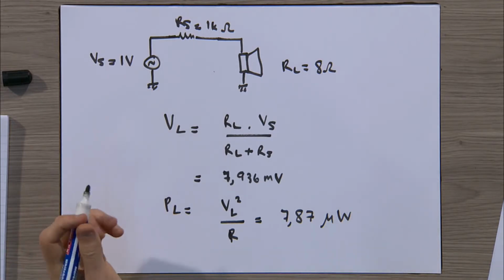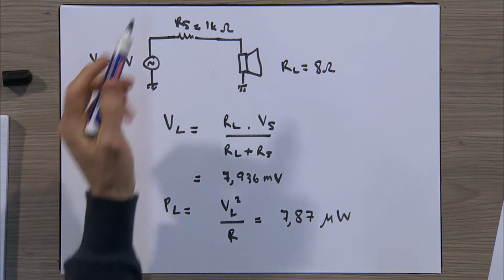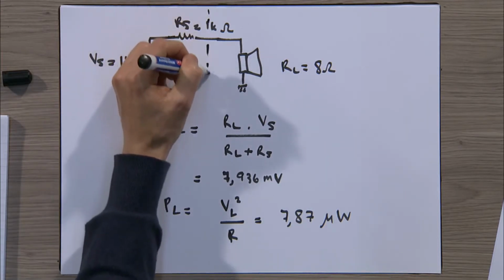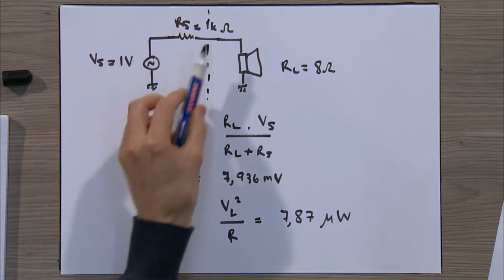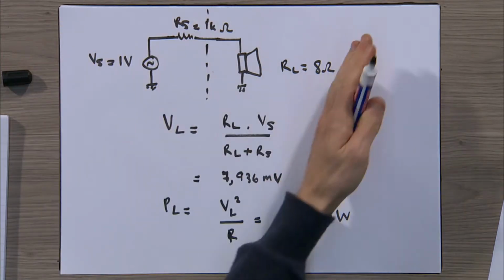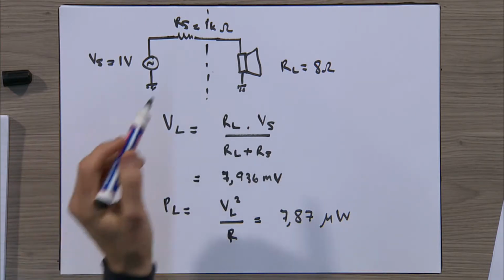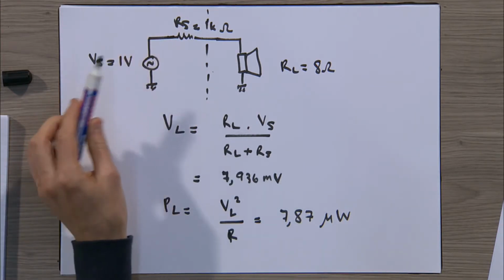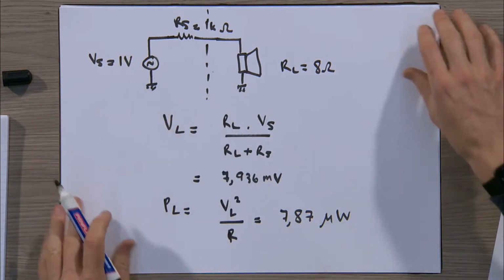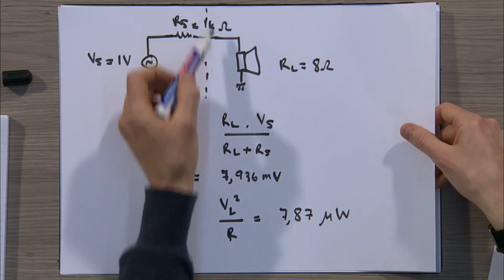So now we can use the buffer to split the circuit in two over here. We're going to use the buffer to separate the microphone assembly from the speaker. And we'll see, without any amplification, it delivers the power more efficiently from the microphone to the speaker. So we're going to use a voltage follower in there. Let's draw that circuit.